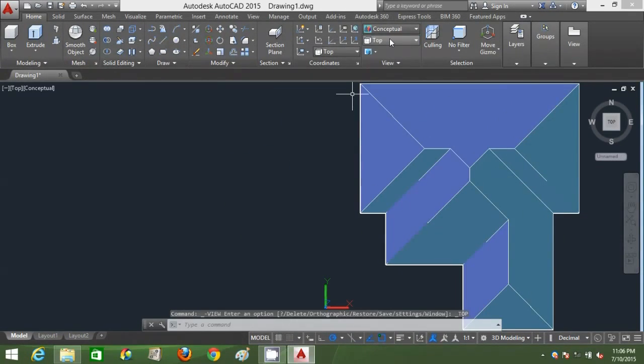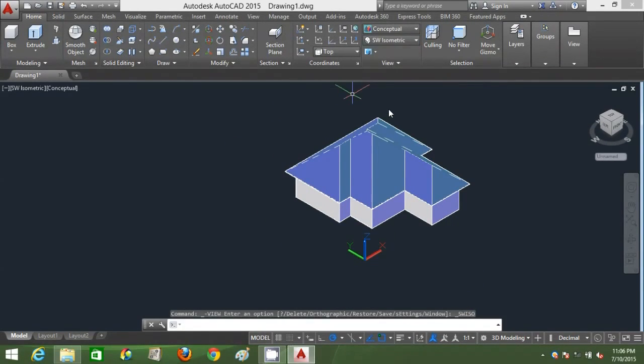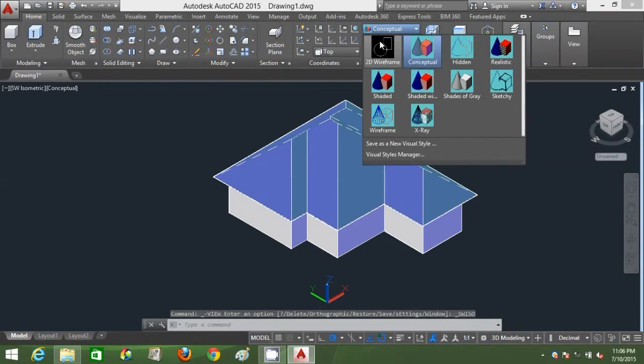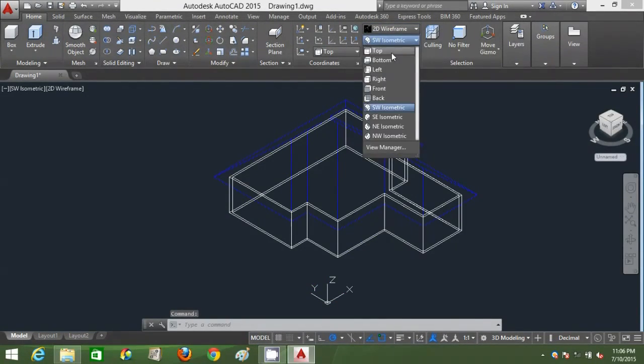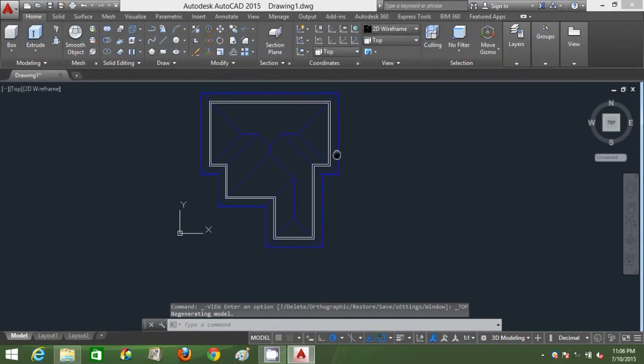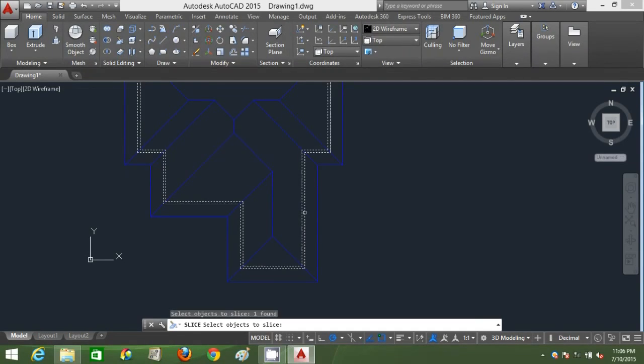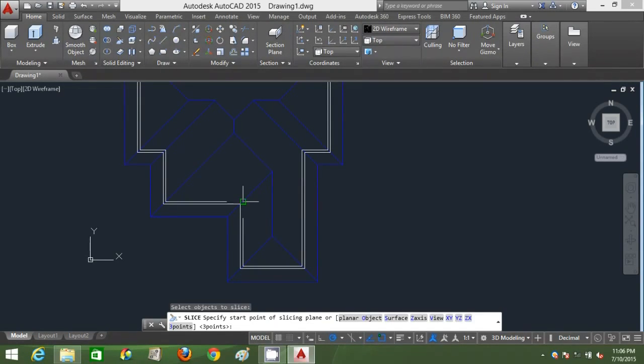it. So you can actually automatically 3D orbit your view by holding on your shift key from your keyboard and by dragging your scroll key from your mouse. Alright, and you can just automatically 3D orbit your view without clicking on the view cube. Alright, without using view cube.